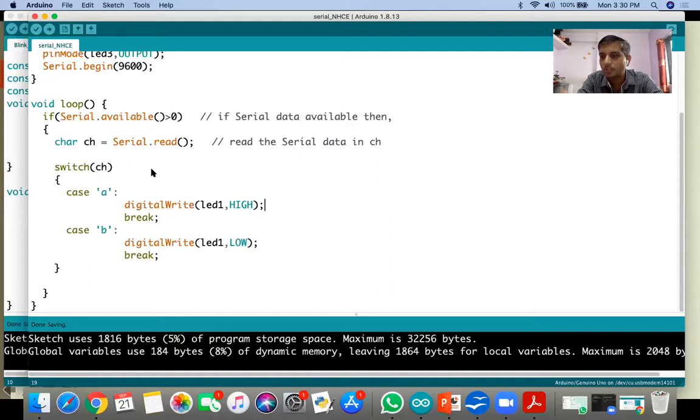Whenever the Arduino requires data through the serial port, that application will continuously monitor the command coming from the Arduino. If the command is the read command, then your application on the computer will read that particular text file and send that data serially. Third-party software is also available.